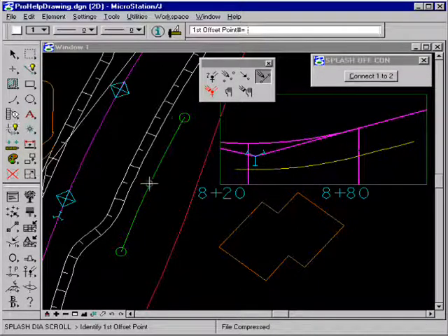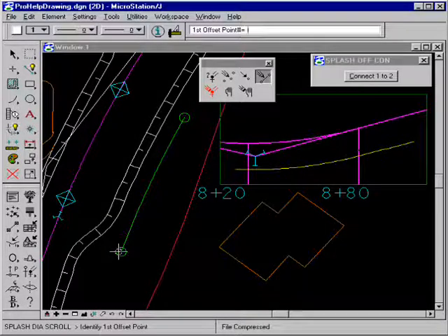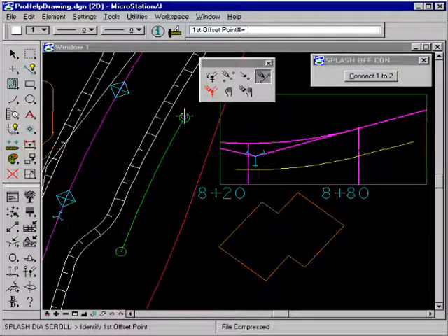I've created a simple two offset point child where we have set the first offset point 6 feet deep below the existing surface and the second point 3 feet deep below the existing surface. And most people don't realize that they can connect the child offset points with different methods than the offset points were created with.